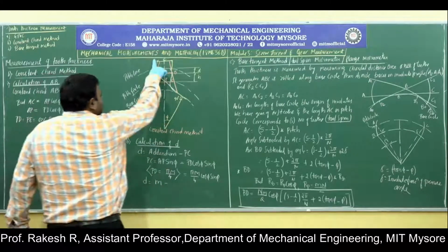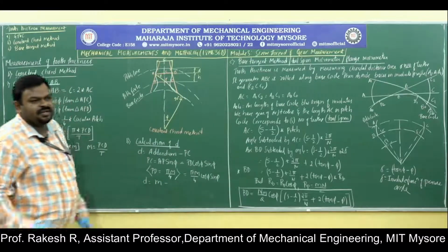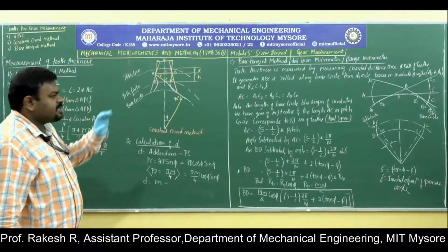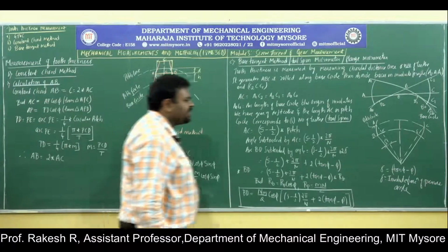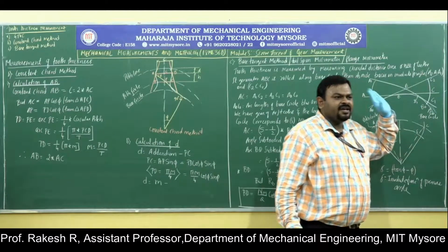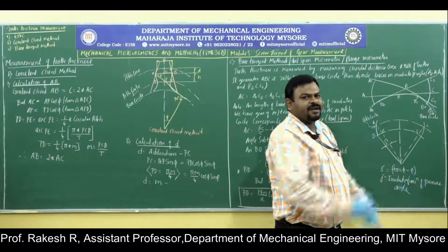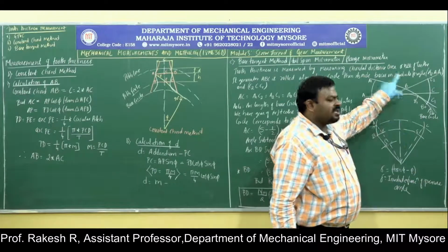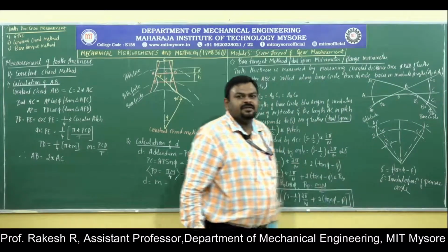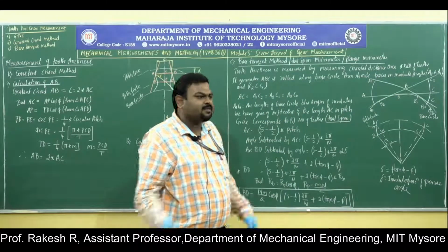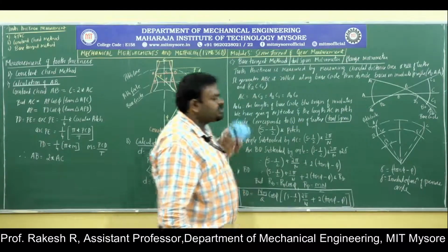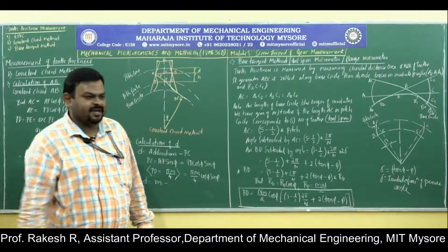In the constant chord method, we are keeping the width as a constant. This portion is made constant in all the teeth and we will be calculating from it. Then in the base tangent method, we are just drawing a tangent to the base circle. It is just like an involute profile where one tooth is cut and then rotated, or indexed, to get the other teeth. It is similar to how a tooth is produced using a mill cutter. The same procedure is the base tangent method.